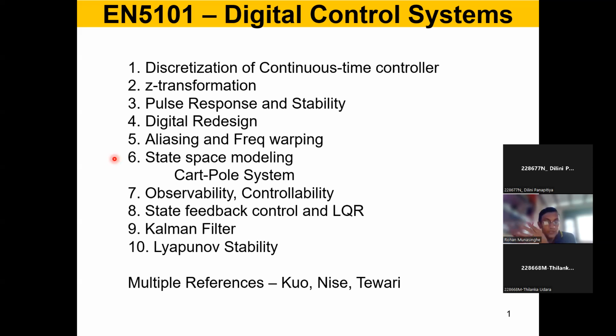Let's call them state variables, right? Can you calculate or estimate all of the state variables, looking at the response, with a few measurements? So you use a few measurements and the plant dynamics, and you estimate the other things of the plant. This is what's called observability. Some plants are observable, which means you can actually estimate the states with the output and the plant dynamics. But some plants are not observable, which means you cannot do that for such plants.